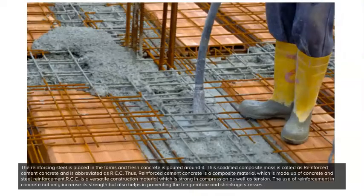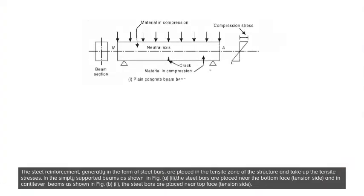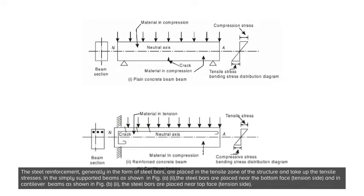The use of reinforcement in concrete not only increases its strength but also helps in preventing the temperature and shrinkage stresses. The steel reinforcement, generally in the form of steel bars, are placed in the tensile zone of the structure and take up the tensile stresses. In the simply supported beams as shown in figure A2, the steel bars are placed near the bottom face, tension side, and in cantilever beams as shown in figure B2, the steel bars are placed near top face, tension side.